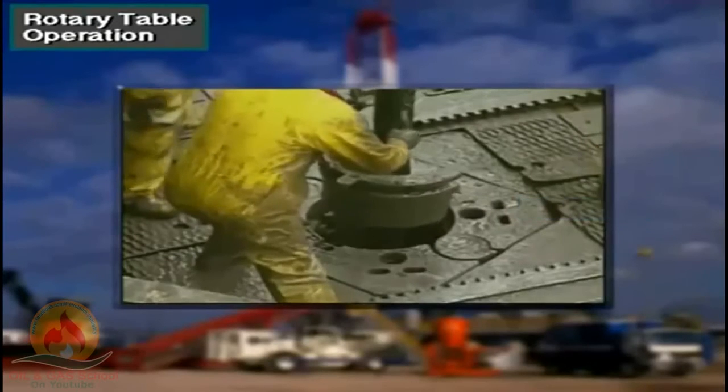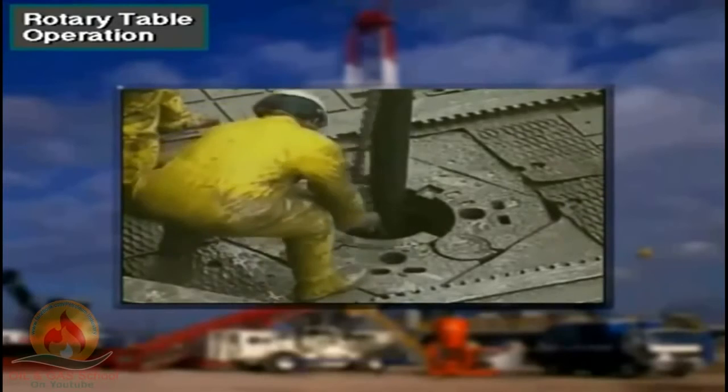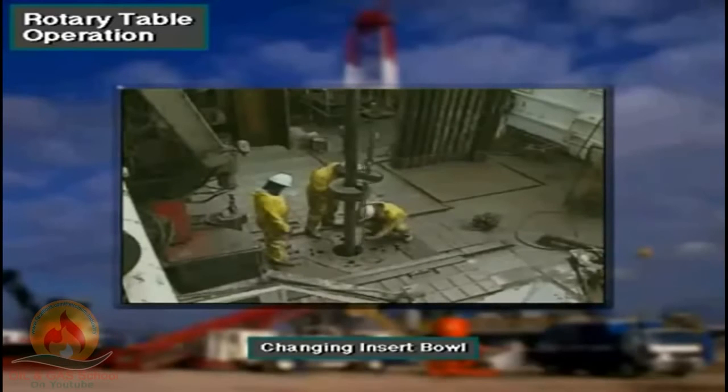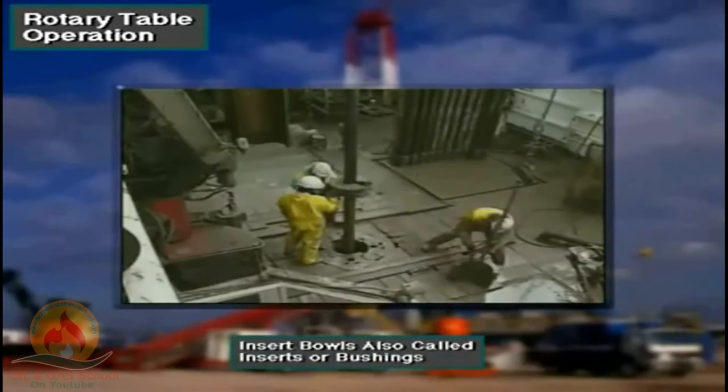Crew members install a 2-piece or split insert bowl in a receptacle in the center of the master bushing. The insert bowl is tapered inside and supports the back of the slips. They come in various sizes. The crew changes out the insert bowls to match the type of slips in use. Insert bowls are also called inserts or bushings.